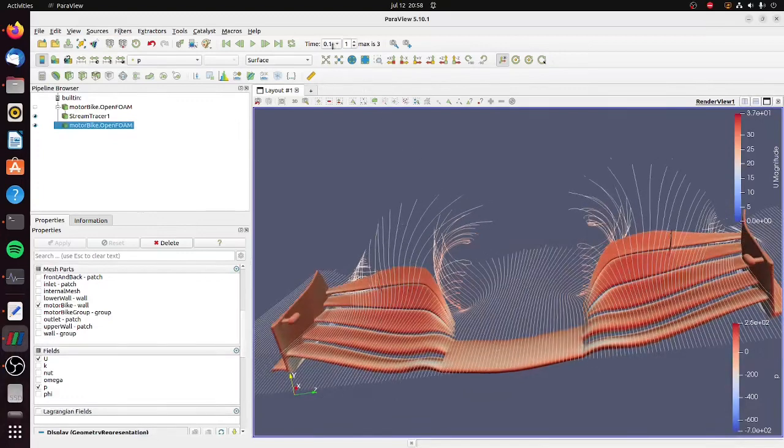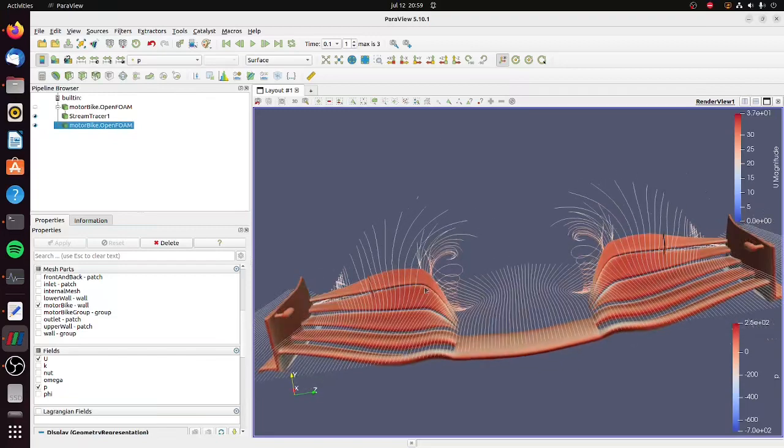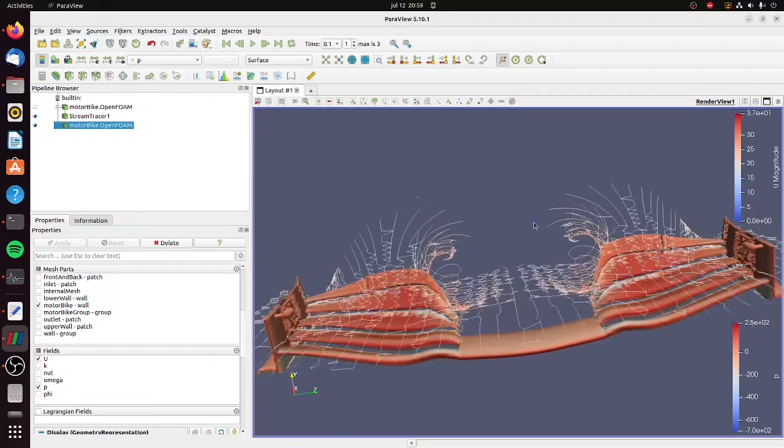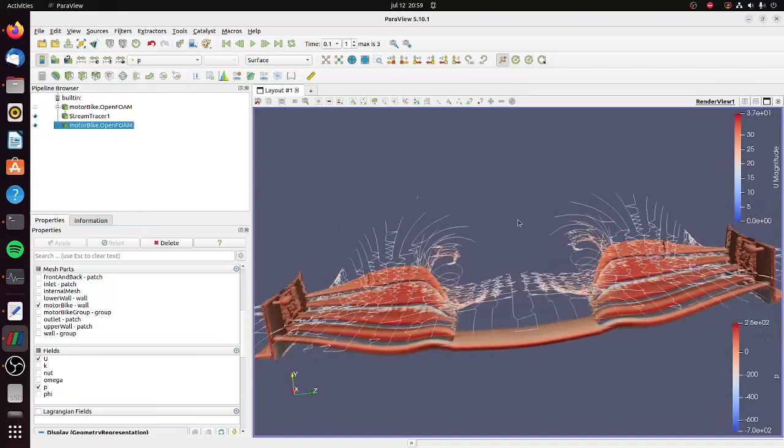What we should also do is test further. So let's go to the next time step. It'll take a second to load, but it should be the same or similar, and indeed it is. They're the same on each time step. So in reality, we actually didn't need to simulate all the way to 0.03. We could just simulate to 0.01, and it's the same as 0.03. It reaches steady state in that time. You know, they're all the same. So this is great.